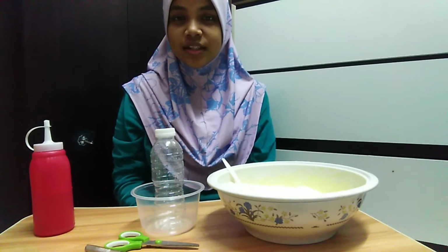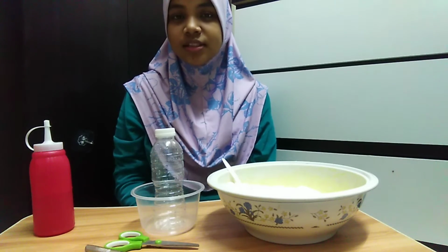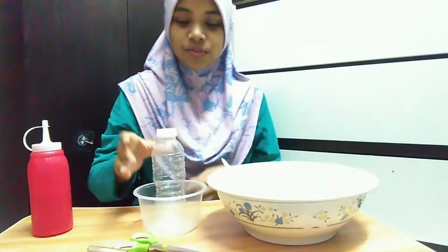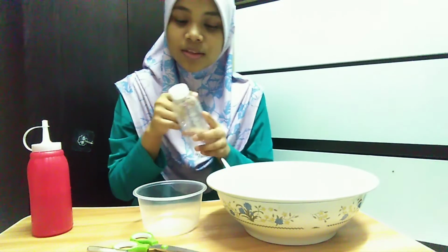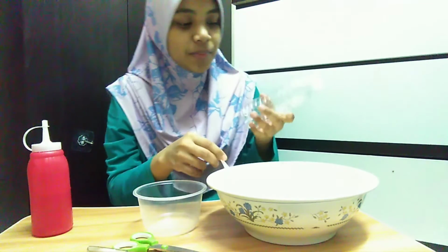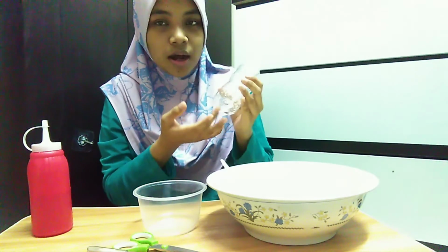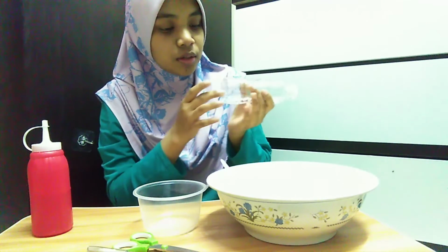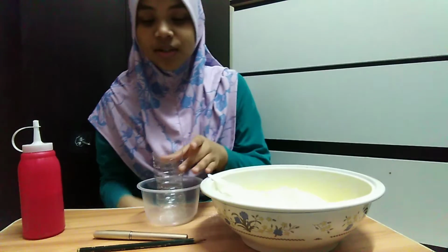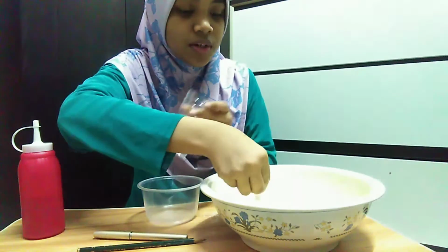For the permeability test, we will use the falling head technique, with a soil sample, falling head apparatus, water, cutter, marker, and tamping wood. Firstly, we need to cut the upper part of the bottle to ease the process of putting the soil sample inside it, and make a hole below the bottle to let the water flow. After that, we put the soil sample into the bottle until around half full.